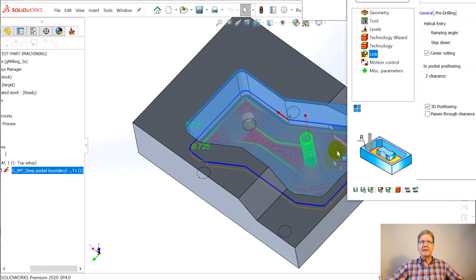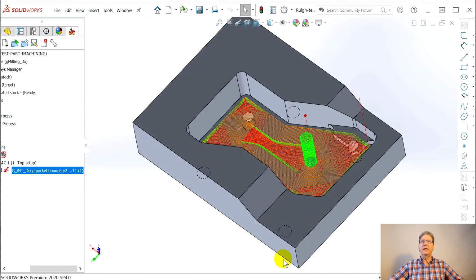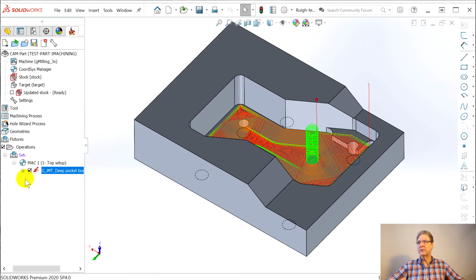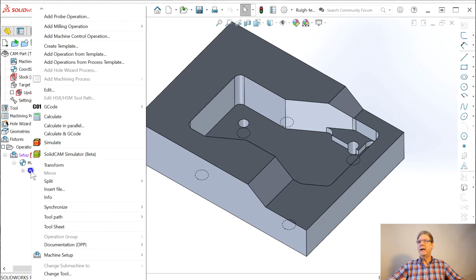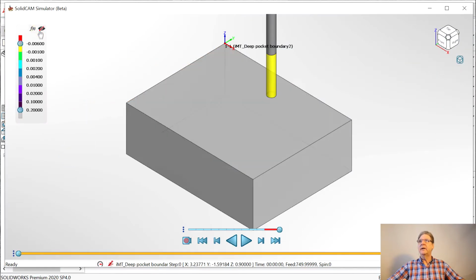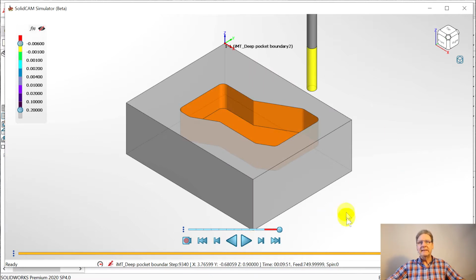And there they are. And you can see it's hovering over here. Now, I've got to get this back where we can deal with it. So let's escape out there. Looks pretty good, right? So now it keeps pushing over. Hide the toolpaths and do the magnificent simulator, their beta simulator. Take compare function off, and go as fast as we can, because you don't want to wait. I might speed this up. I did see down here is the machining time, 9 minutes. So it took 9 minutes to do this.